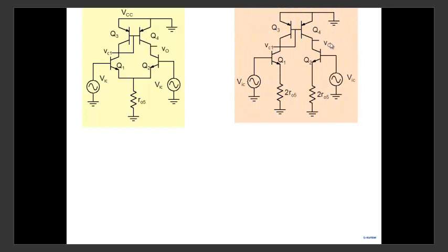There's a problem. It's not symmetrical. Please keep in mind, it's not entirely symmetrical. Note that this is shorted here and this is no longer shorted here. Okay, so it's not symmetrical, but we are carrying over our notion of symmetry from previous cases, and we're saying, well, let's apply it. Assuming that this voltage is also very small and comparable to VC, then when you look down, you see Q1, Q2, below this particular plane, everything is symmetrical.